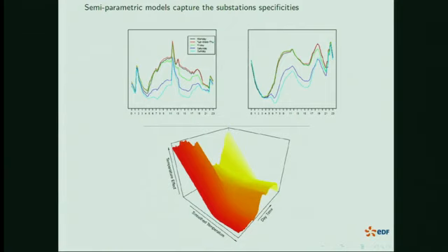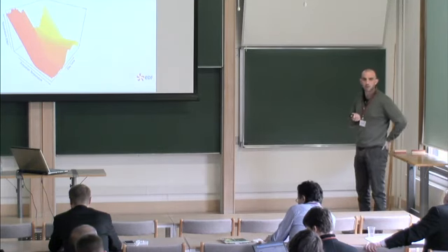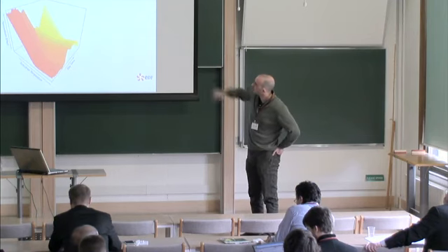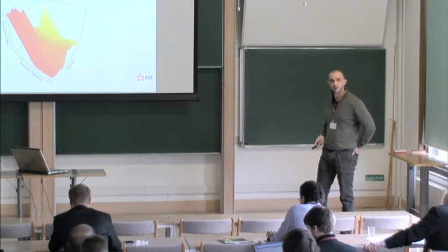So we have fitted GAM models also automatically on this data. It worked quite well. You can see here different effect estimates. So this graph is the temperature effect over the day for one substation. We can recover a specificity of residential consumption in France because of off-peak and peak tariff. A lot of people warm their home in the night because the price is lower, and you can see it on the graph. And you can see the effect of off-peak and peak tariff on the left with spikes on the estimation curve.